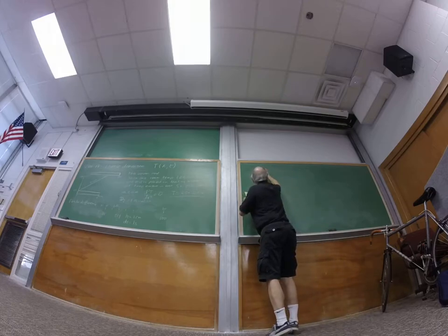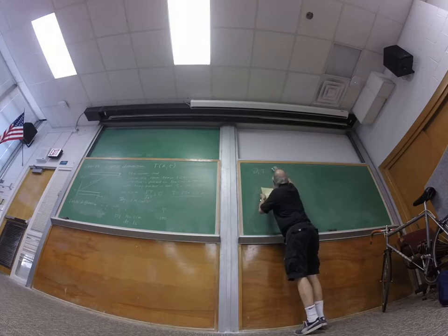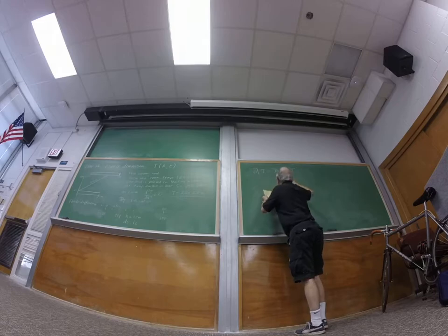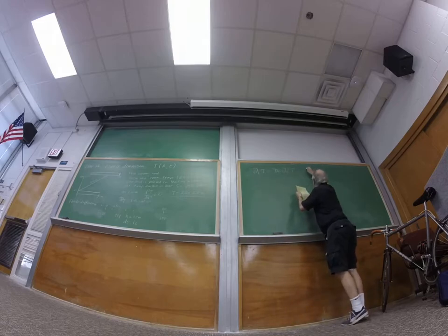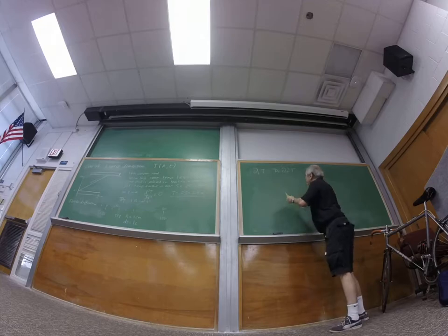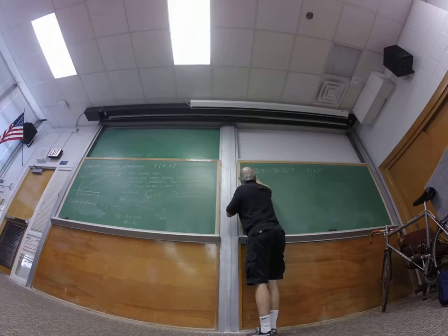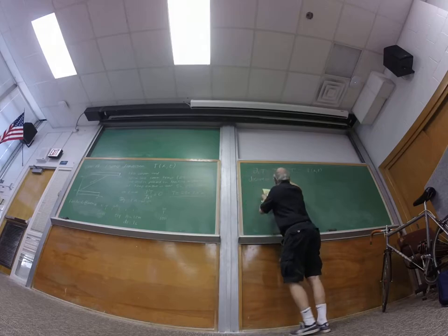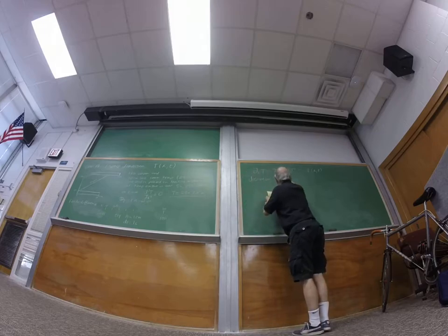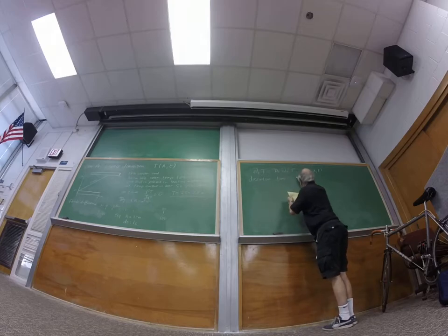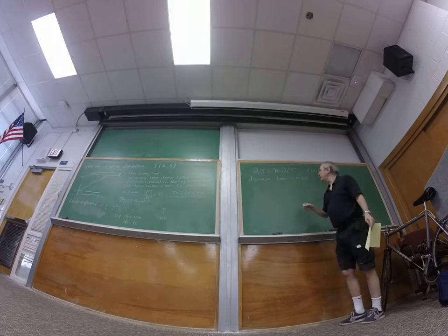So once again, this is the actual partial differential equation that we're trying to solve. And in this case, the temperature is a function of position and time. So in order to use finite differences, I have to discretize both space and time. So I'm going to discretize time by making it into some integer multiples of the time step, okay?